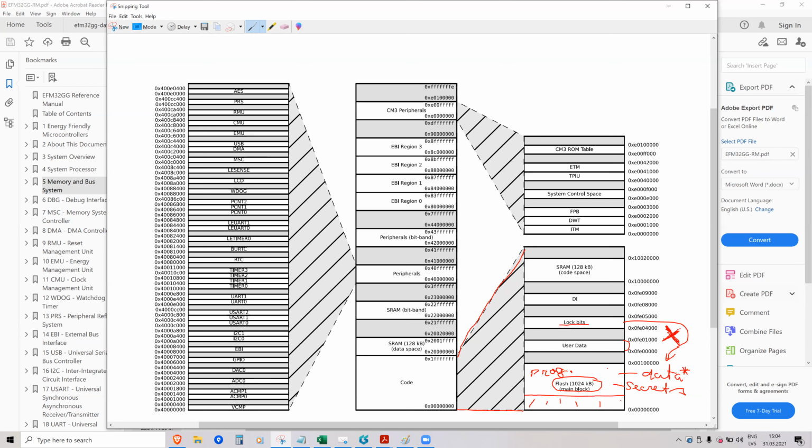So these microcontrollers have this feature, and actually most other microcontrollers also have a feature where you can lock the flash memory against reading. And everybody actually does it commercially. If you try to read, for example, iPhone's flash memory, it will probably also erase itself. It's impossible to read it. It's all locked. So secret information you can also store in the flash memory, because if somebody tries to read it and you have locked it from software using one function, which is the lock flash function, they will not be able to read it and it will erase itself.